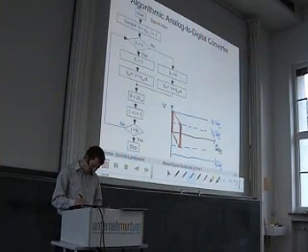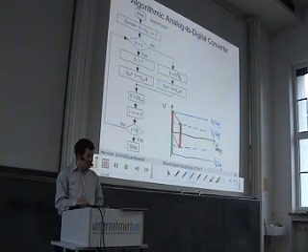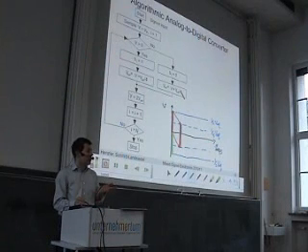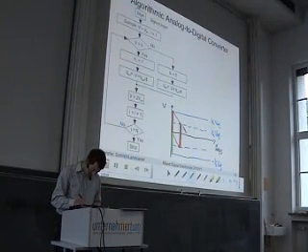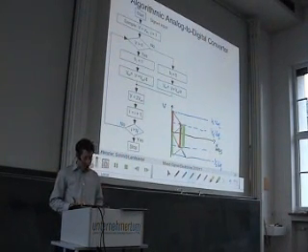For all voltages that are negative, so for all these green voltages, we say V larger than 0, no, so set the bit to 0 and add Vref/4. So the green voltage bar goes here. So this one goes here, this one goes here, and so on.